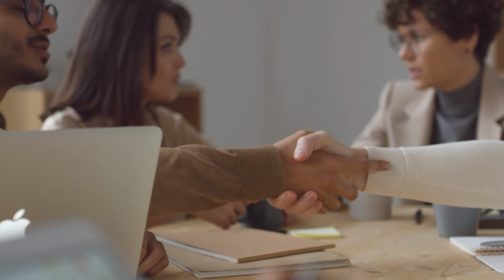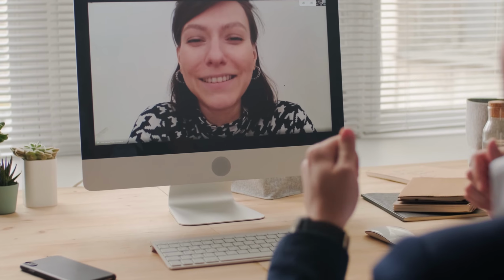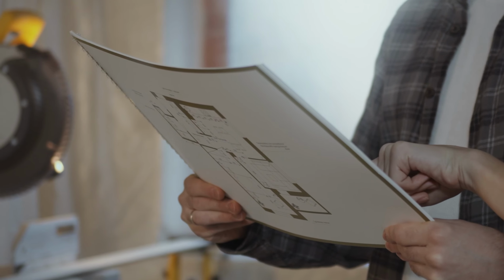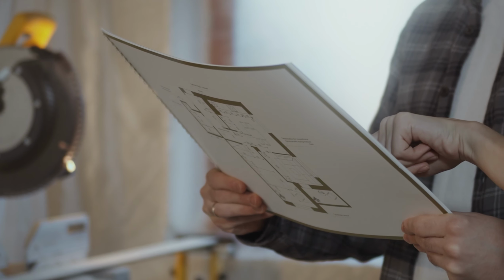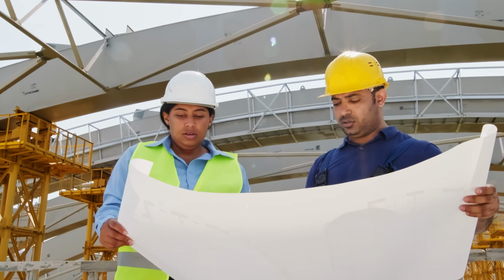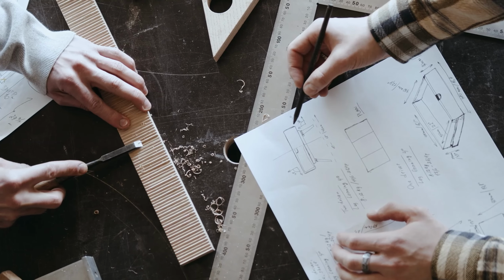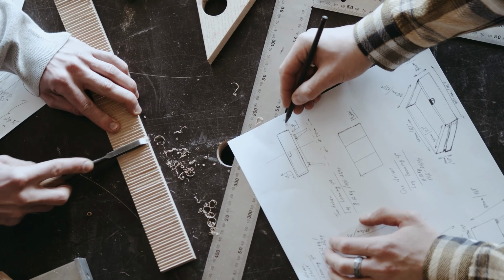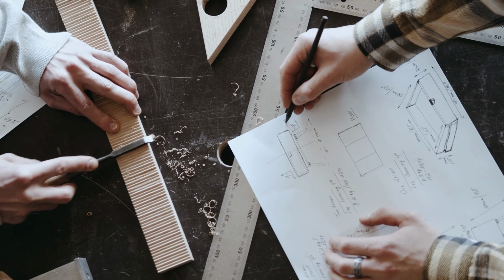This means that after manufacturing, if the diameter of the part is within the range of 19.95 millimeters to 20.05 millimeters, it is acceptable and can be brought back for us to use. By providing this GD&T specification, we ensure that manufacturers understand the required dimensions and can produce the shaft accordingly. It eliminates ambiguity and allows for consistent communication of design requirements.